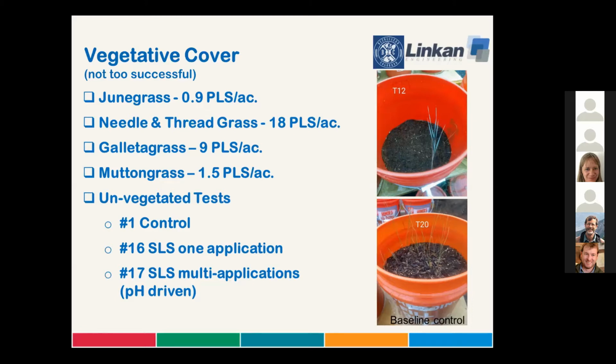We used the same one that the DRMS would have used on the site, and we multiplied it times 3. And 3 test cells didn't receive any seed at all. And as you can see in these photos, the revegetation experiment wasn't very successful. However, we think that the plant growth media on the surface may have prevented some oxygen exchange. Again, we're cutting off another leg of the ARD tetrahedron. And we've had this problem on other projects.